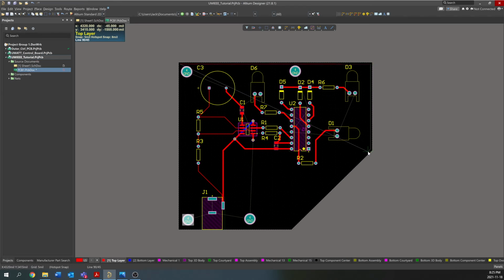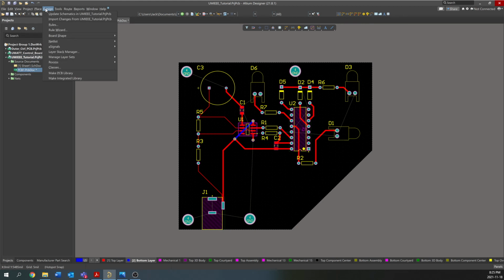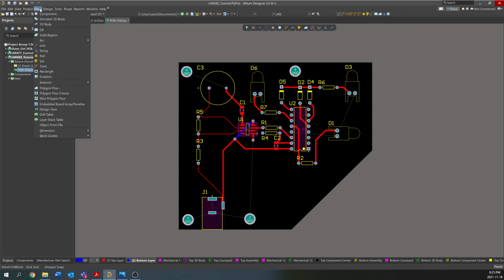Across the top here, down. And actually, I realized here I'm starting to route this polygon pour on the top, and I don't want to do that. So I'm going to make sure to switch down to the bottom layer here. And NavDot's noted that we use 4-layer boards to give ourselves more room to route traces, and that's 100% true.